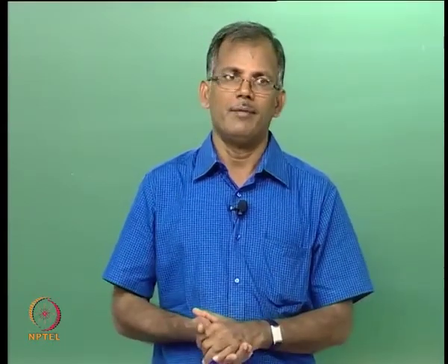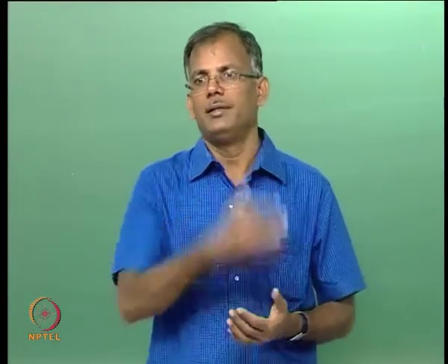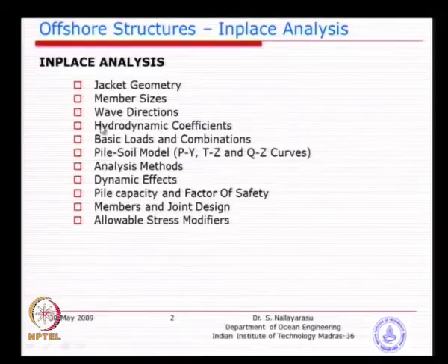Whether it is a main leg pile or skirt pile also has to be decided depending on the site. If it is a 100-meter water depth, maybe a main leg pile is no good. I think I have already explained why, because the pile is going to be inside, unnecessarily increasing the weight. So, you can have a skirt pile on the side, so that you can reduce the weight. Member sizes, wave directions, hydrodynamic coefficients you will see later on. Loads and load combinations: what loads can actually coexist at any time during the operation.